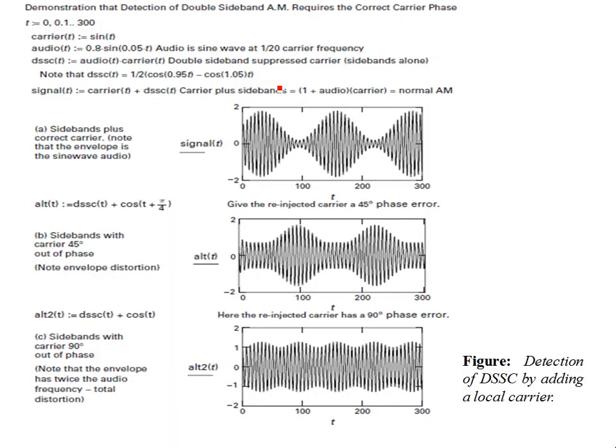The problem that we discussed before was, if you have a double sideband suppressed carrier signal and you add the carrier with the wrong phase, your envelope no longer reflects the original audio signal. Whatever it is, it's different from what we transmitted. What we desire is like this, but if the phase of the carrier is not correct, the envelope gets distorted. So we don't need this envelope.